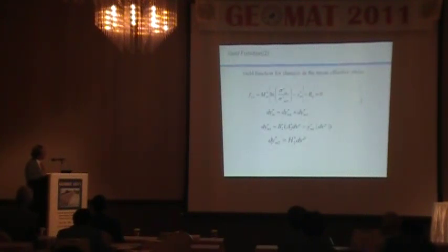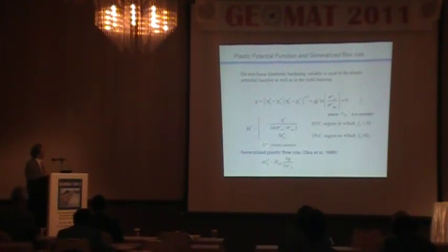And for the change of the mean effective stress, we adopted a secondary function, which means it is non-associated. Of course, we need a plastic potential function because it has a plastic stability. G equals zero is the potential function with the same kinematic hardening parameter chi_ij and with the delta coefficient. It may change outside and inside the boundaries.